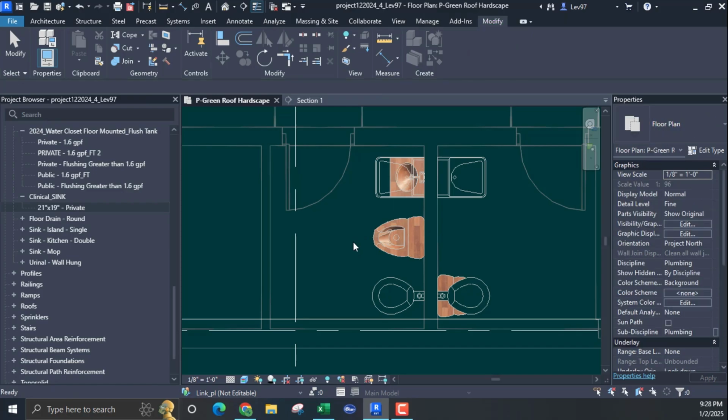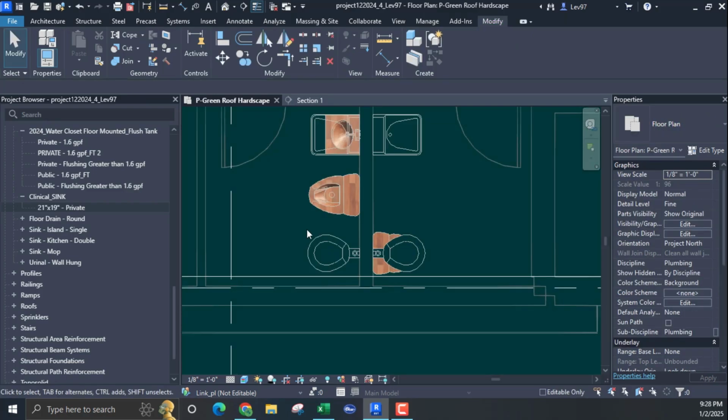I don't like to do a mirror because sometimes if you mirror it and you do the same process of getting a piece of pipe, and in this particular case the pipe is right, have it go down into the floor, and if I mirror the plumbing fixture, it may go up toward the ceiling. So I don't usually mirror my plumbing fixtures.